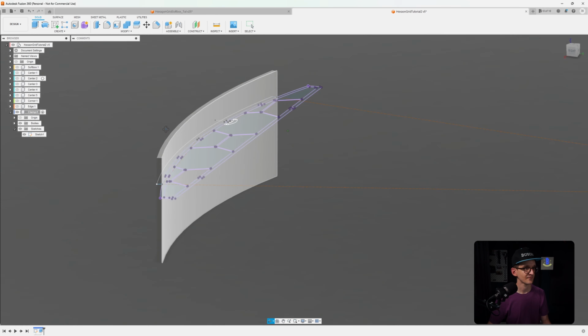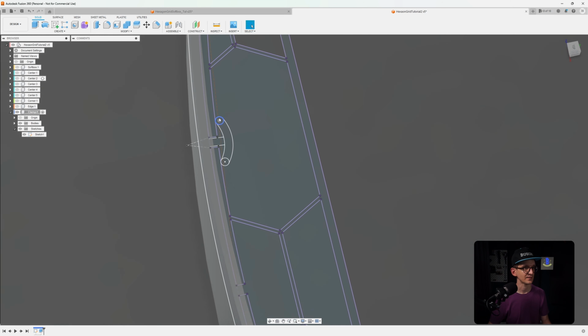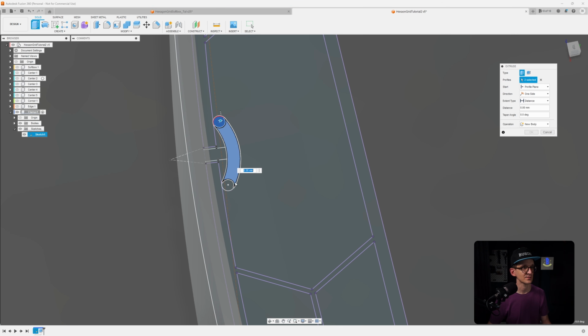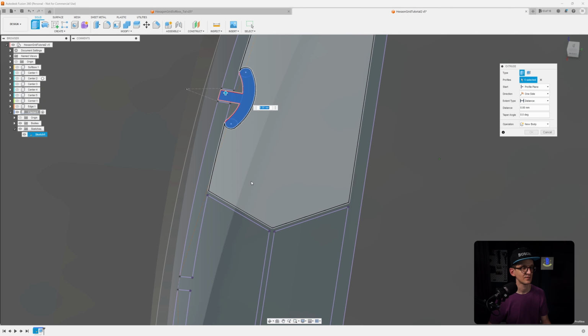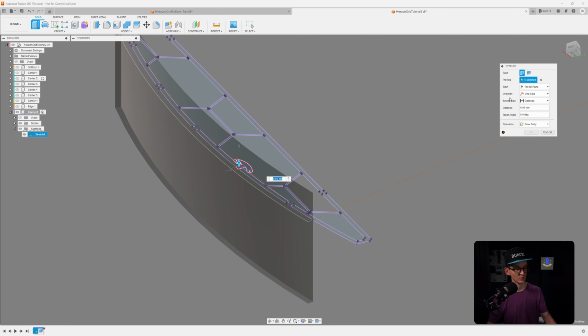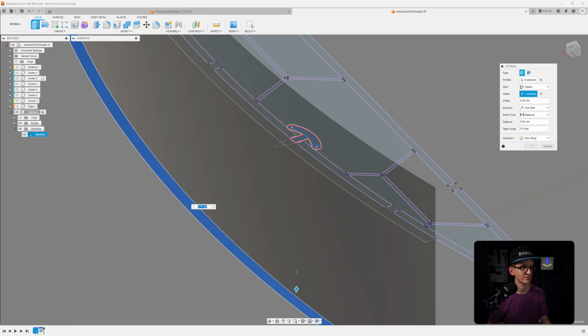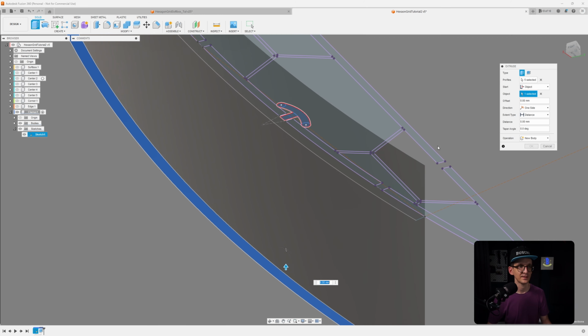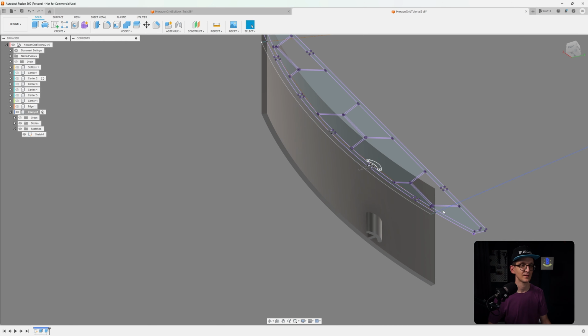And then as the next step, now I need to get the sketch back and make sure that the clamps are there as well. So I select the outline of the clamp. Again, same procedure. We go to the underside because here's where the slits in the profile sit. And from where we would like to reference it, we go to Start, Object, and select the surface here. And then we know that the slits that we created are 8 millimeters deep, like so. And instead of joining, we are now creating a new body because we need to replicate those first, and then we can join it to the clamp. So that's what I'm doing.